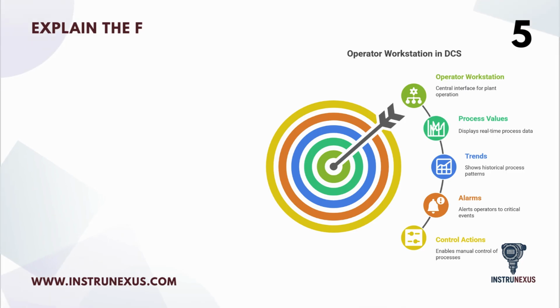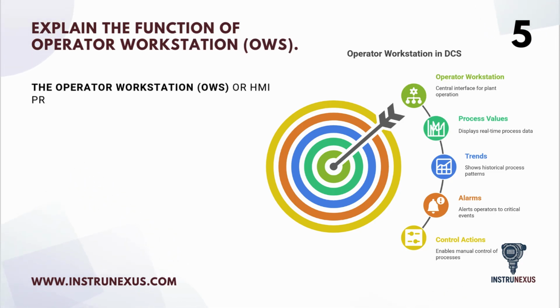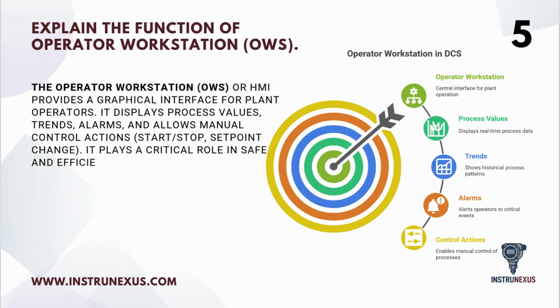Explain the function of Operator Workstation, OWS. The Operator Workstation, OWS, or HMI provides a graphical interface for plant operators. It displays process values, trends, alarms, and allows manual control actions, start/stop, setpoint change. It plays a critical role in safe and efficient plant operation.